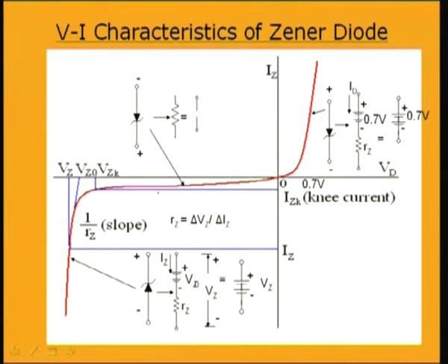So, this Zener diode in the reverse bias condition, the negative terminal of the battery applied to the Zener diode is connected to P and N is connected to positive. This is the symbol of the Zener diode. It is a crooked N to differentiate it from the normal PN. So, this region can be equivalently expressed by only the resistance, which is very high.